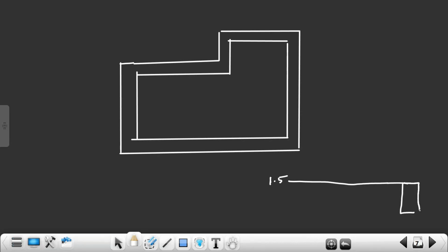This 1.5 volts you are connecting to the cell here. Is this cell going to get the same 1.5 volts? No. Because this metal layer has resistance. When the current is flowing through this metal layer, it also has some resistance. Every metal layer has resistance. If metal length increases, resistance also increases.